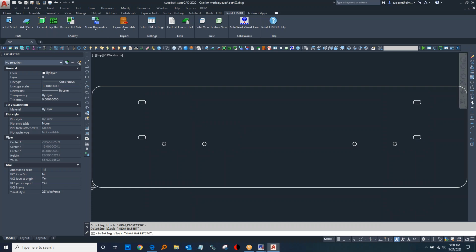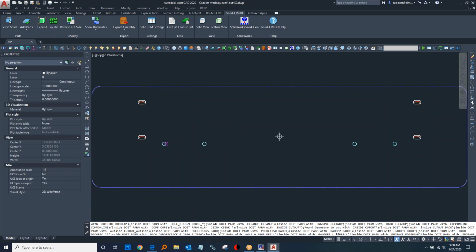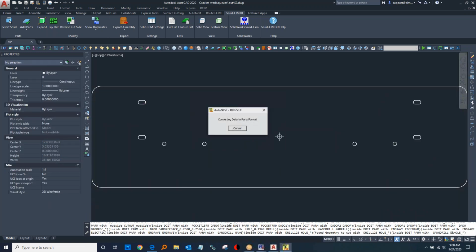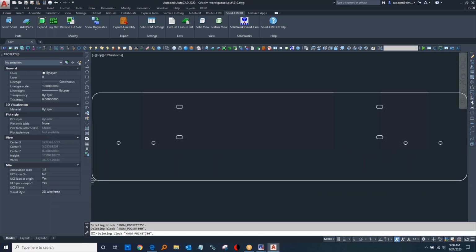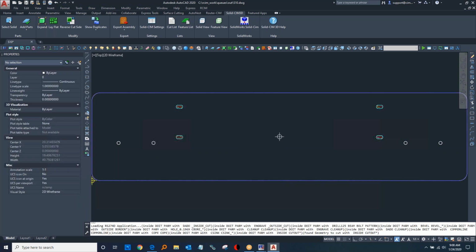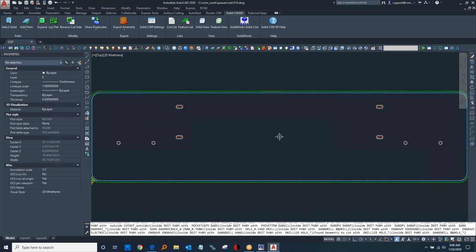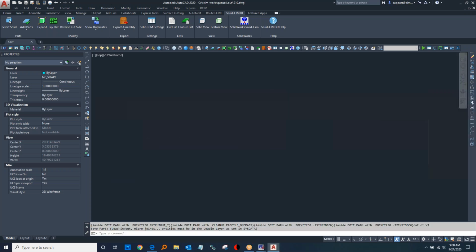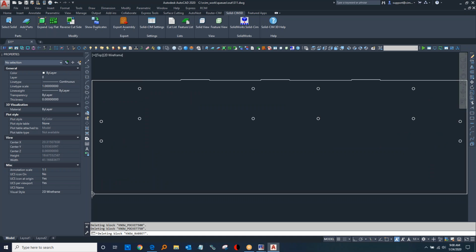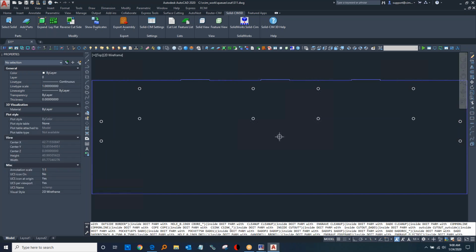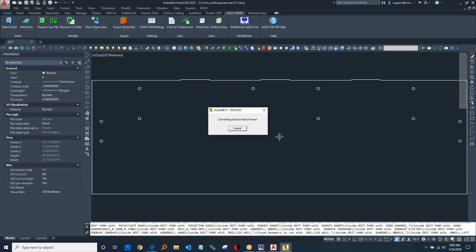We're also going to be able to do skeleton cutting, where we can use the router to chop up any of the remnants on the table. We have scrap management, a rolling scrap manager to save the scraps. There's a full labeling system built in the RouterSim. We'll get all these results here in just a few seconds. And I'm going to get all these results really with just 2 clicks. One click to select the solid, and the other one to cut on the cut list. Let's let the parts process and then come back and we'll look at the results.